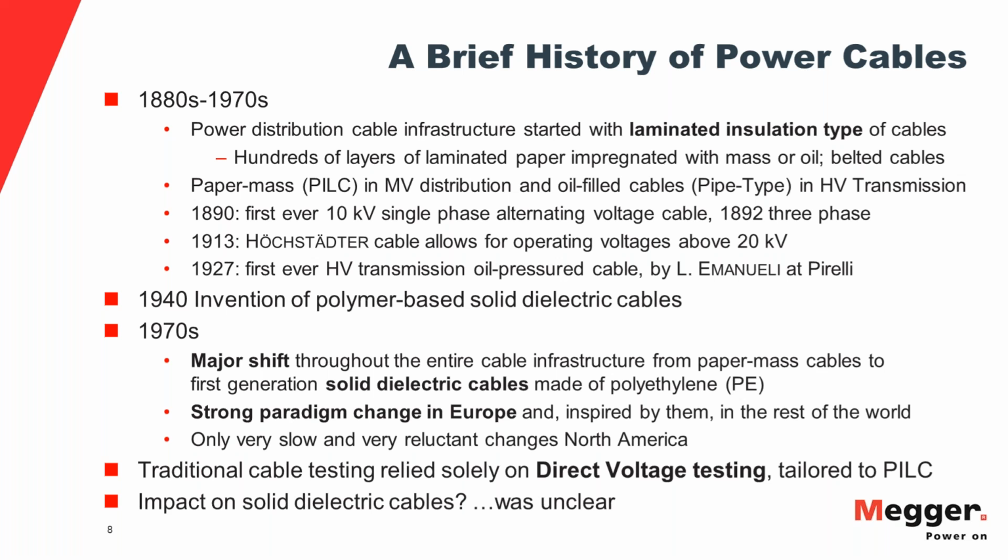So then in the 1940s, the plastic technology evolved quite a bit. And in 1940, the first solid dielectric cable was manufactured. However, there was not a big breakthrough or anything. It was just there. In the 50s, there was a lot of PVC put in, which haunts us today because PVC is a terrible insulation material for cables, high losses, and should not be used anymore at all.